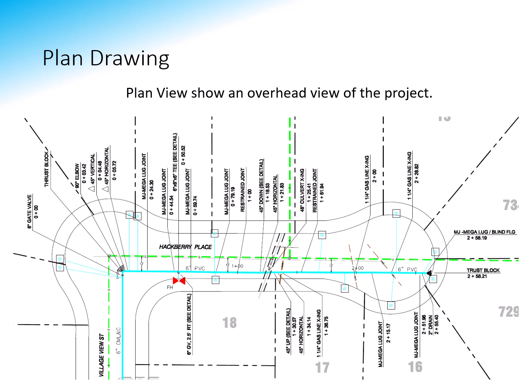Here we have a more close-up view of the plan drawing, right? The plan view. And you can see in here, if you look real closely, that stationing in there that's calling out where these are located, right? Where are these service taps? If you follow that line right there, it's telling you where on the main that service lateral for this one right here is located.